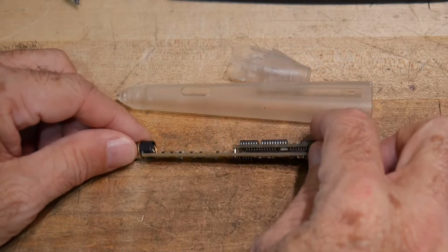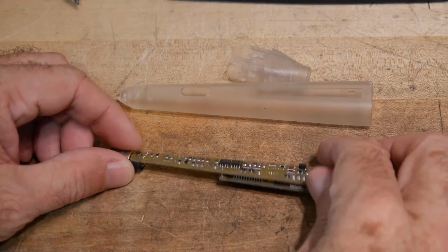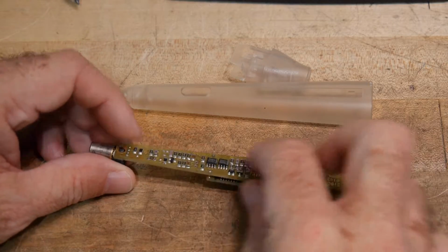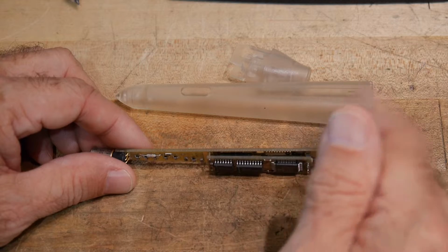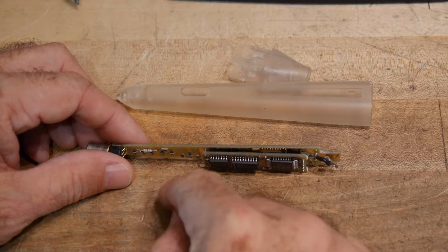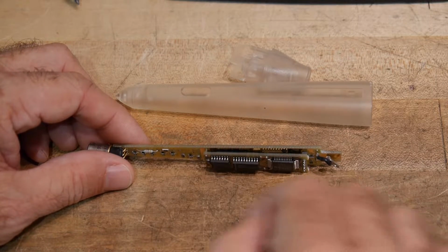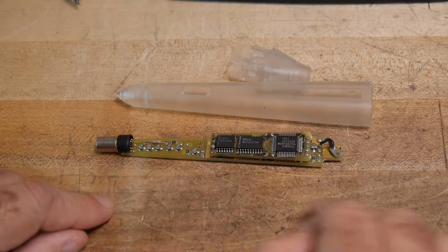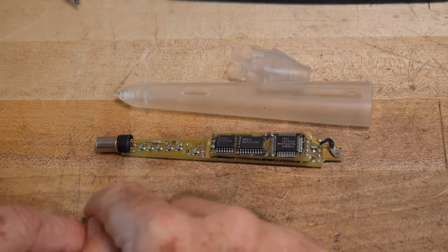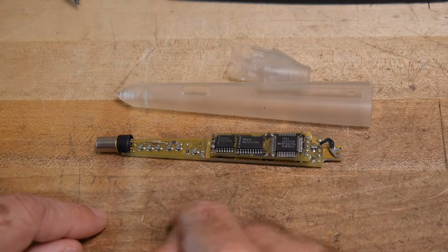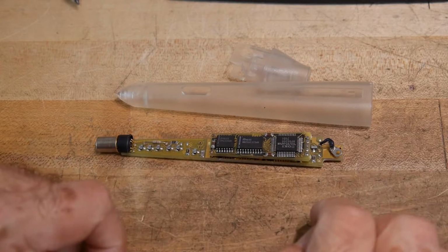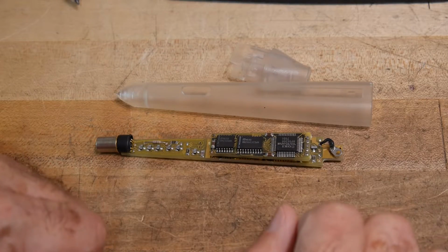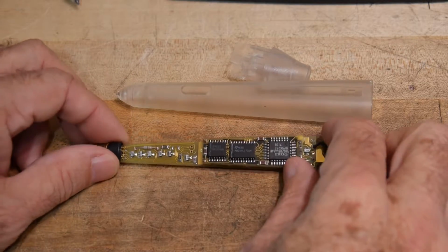This particular device was what we called a smart wand. Some of the wands were dumb, and all they outputted was ones and zeros. As you went across the barcode tag, it would just send out 00110101. In fact, it wouldn't even send out zeros and ones. It would send out the analog waveform, so it would just shape the waveform and send out a pulse train. And then it was up to the circuit outside to figure out what a 1 was and what a 0 was, and how to do all the acceleration stuff and things like that.